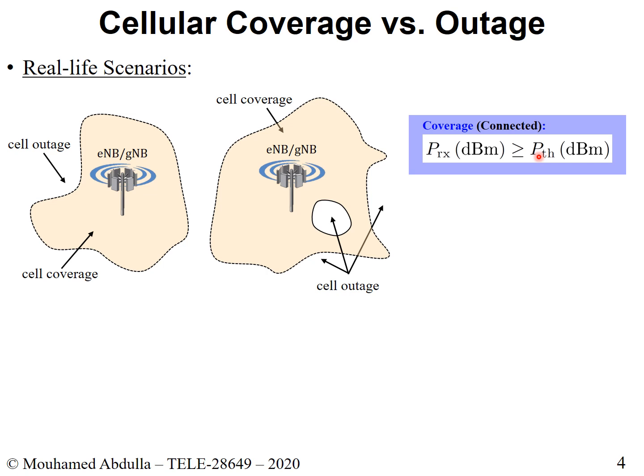If you don't like minus 110, you can memorize minus 100 dBm, that's a good way to memorize it as well. I think it's fair to say that if you have minus 100 dBm and above, you should have a reasonable signal, perhaps 1 or 2 bars, and that should be fine. And if you go below that, then you're not good. And this one is essentially the power that you receive. The power that you receive, you could just identify its value.